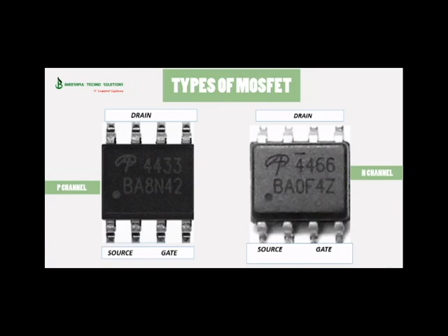In the case of an N channel MOSFET, keep the negative probe at the drain and the positive probe at the source. It should show a reading between 300 ohms to 550 ohms. The remaining checking is the same as for P type MOSFETs.